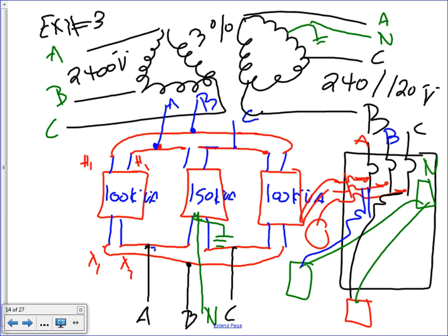Unless you're doing three-phase or two-phase. Like, if here's the two-phase, do I have a two-phase here? I don't have two-phase. I can use two phases. For example, can I use A and B only, just A and B to feed the load? Yes, A and B. But not B and neutral. What voltage does A and B get? A and B is 240 single phase. Oh, I thought A and C was 240. Both of them, all of them.